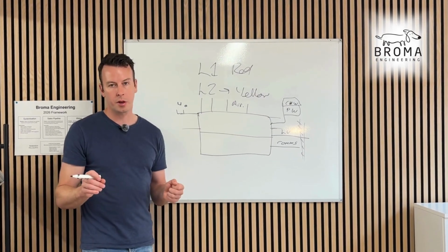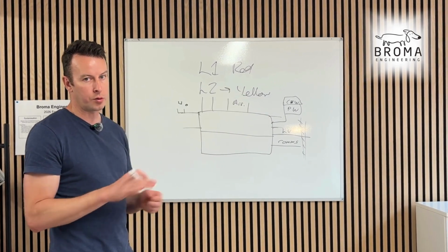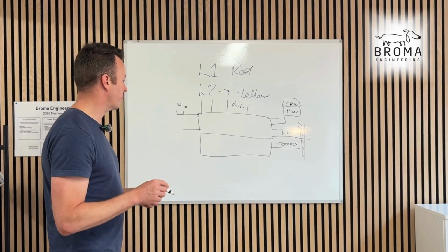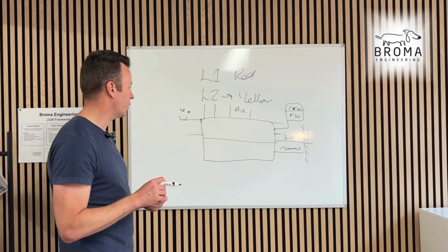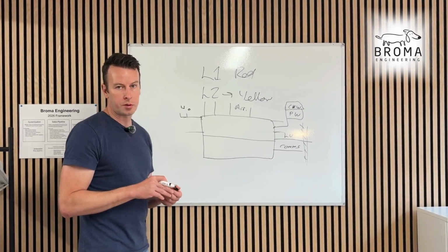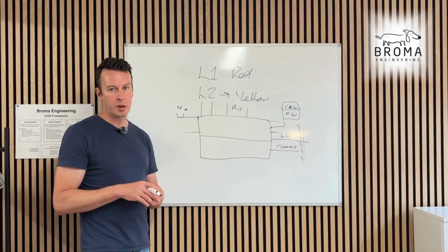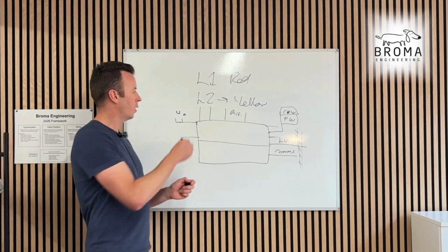Engineers have signed off on it. We're not changing pipework at the end of level 2 when we have no time. So be very careful. Cross your T's and dot your I's in pre-construction. Get it all in there. Get it in there as part of a technical submittal. And don't try and slip it under people's noses. Try and highlight it in meetings and say, look, this is what we want to do. We want to get everything signed off early.